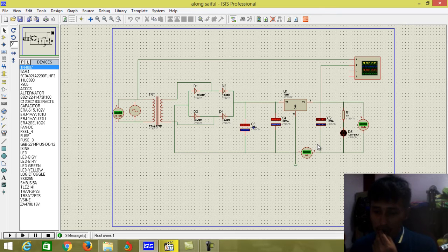So the DC is current, positive or negative, with respect to ground. This is the ground. It also has a ripple. Ripple can be defined as the departure of the waveform of a rectifier from pure DC. Ripple is the amplitude deviation, positive and negative, of a waveform from the pure DC value, the AC component of the rectifier voltage.